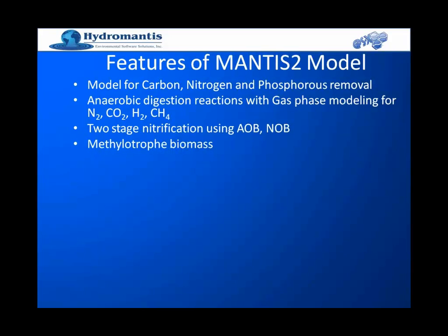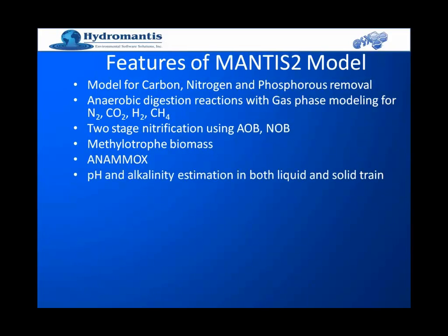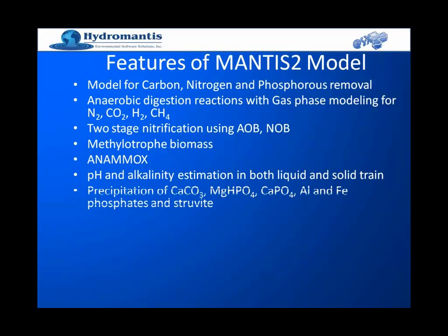Also, we have included a methylotrophic biomass, because methanol, which is sometimes used for denitrification, can be consumed only by a specific group of bacteria. So we have a dedicated bacterial group for degrading methanol in the model. We have also included the ANAMMOX bacterial reactions in the model. The model also estimates the pH and alkalinity in both the liquid and the solid trains.